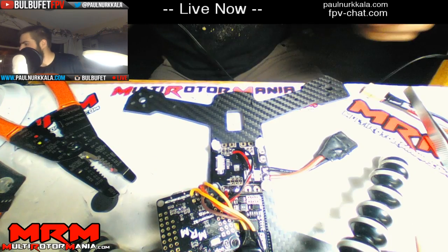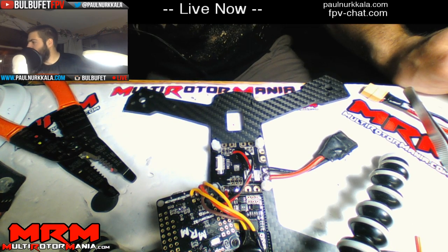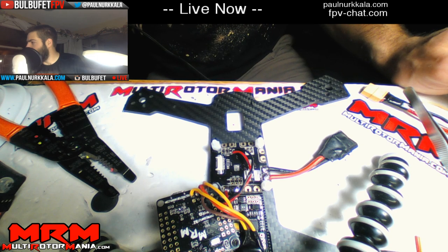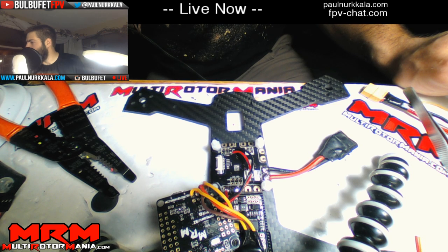Paul, you want vid signal and ground to go to the OSD. Send only power to the adjustable BEC output.